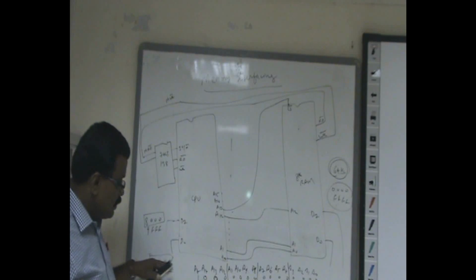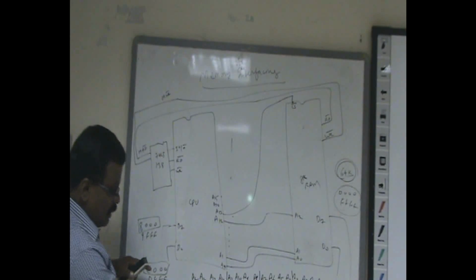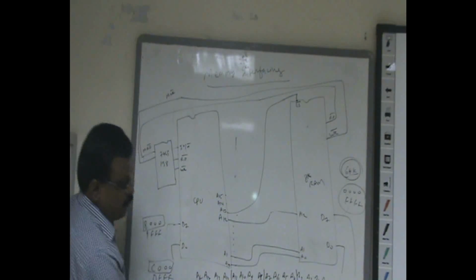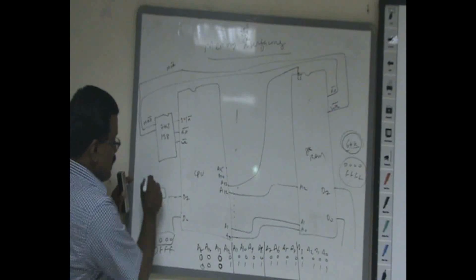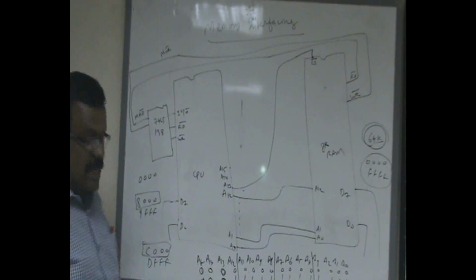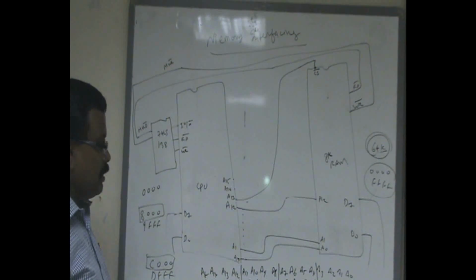Whether you specify C000 or A000 or 0000, all may point to the same location. So you can say one more duplicate address is 0000. So every address will have 4 duplicating addresses. It will lead to a lot of confusion.